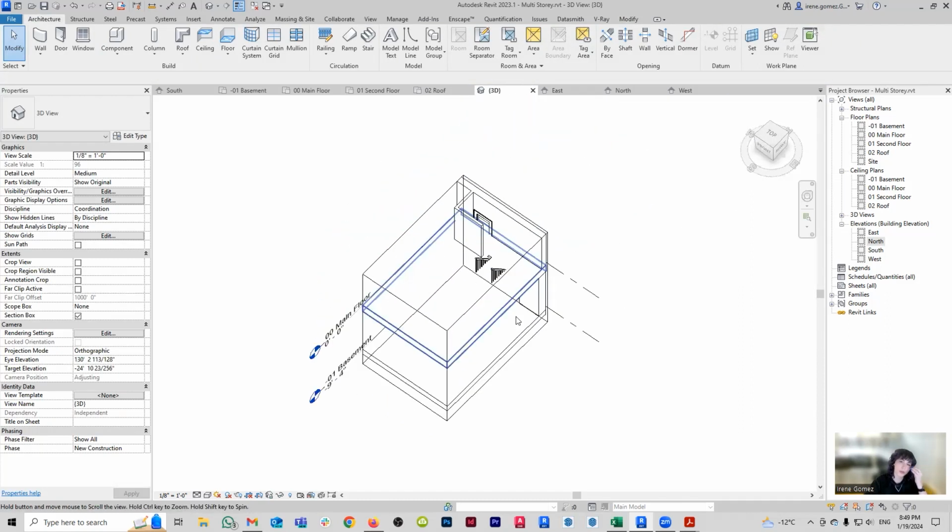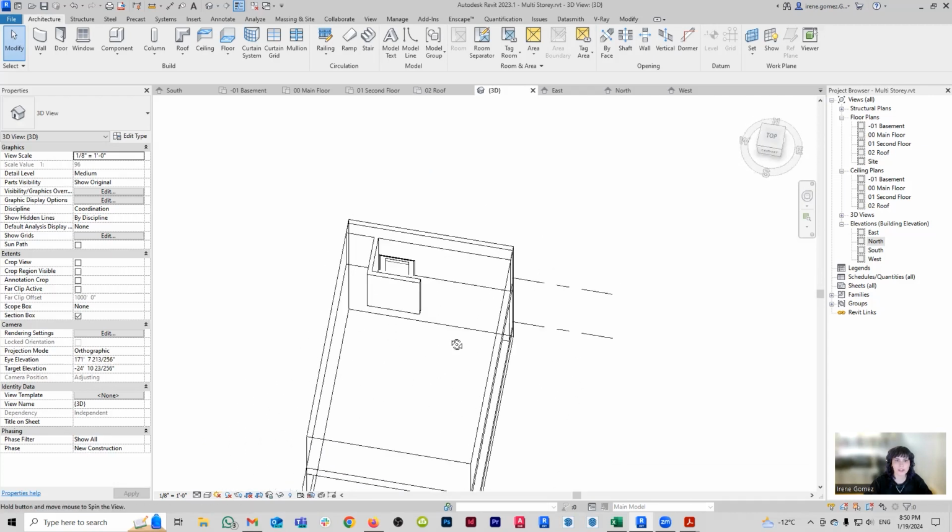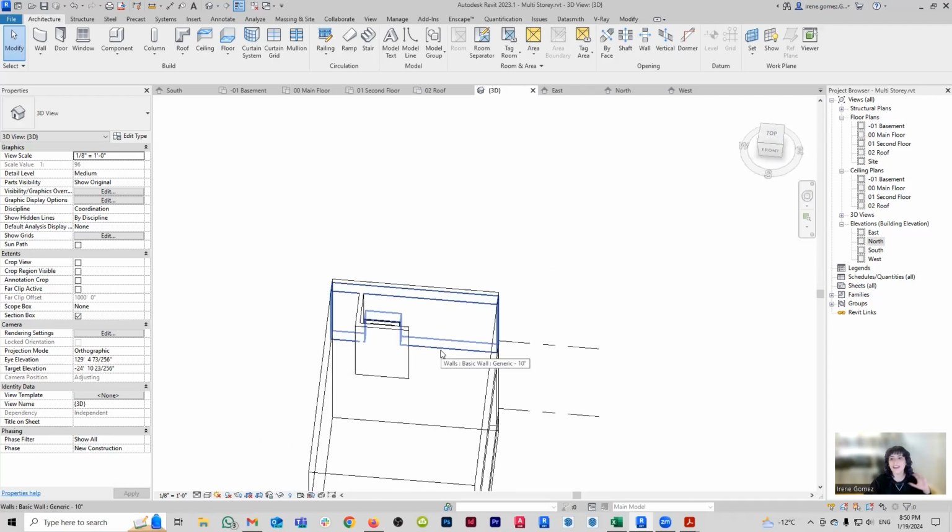So basically what you can see here is that you don't need railing everywhere, and the type of railing that you need is not necessarily this one. So what I like to do is actually, once again, make my own railing. So you can just select this guy, delete, select this guy, delete. So before I make my new railing, let's fix the opening. So now that you have the stairs, you can do the opening.